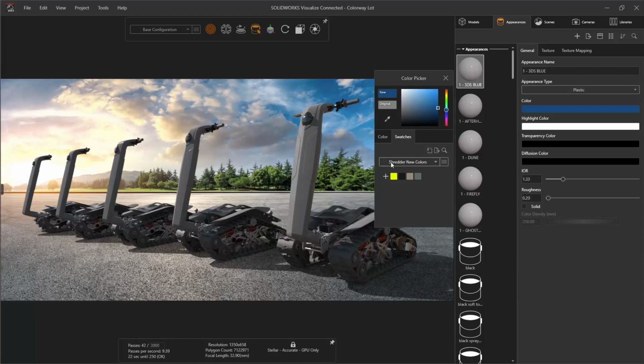With a colour chosen, we can add the swatch to our palette and lock the palette to prevent any further changes. Palettes can be exported as a shared asset across users or imported back into SOLIDWORKS so that accurate colours can be applied in the design phase. The previous 8 colour selections will also remain in recent colours across all sessions. This dramatically enhanced colour management system ensures that your exact colour is never more than a few clicks away.